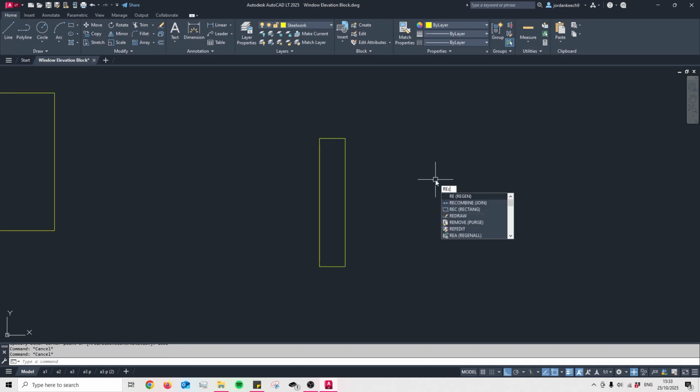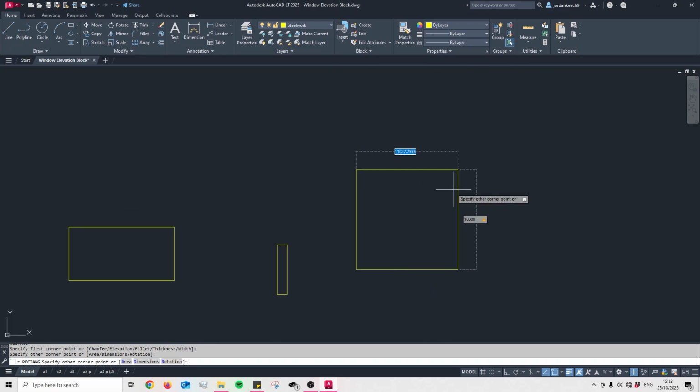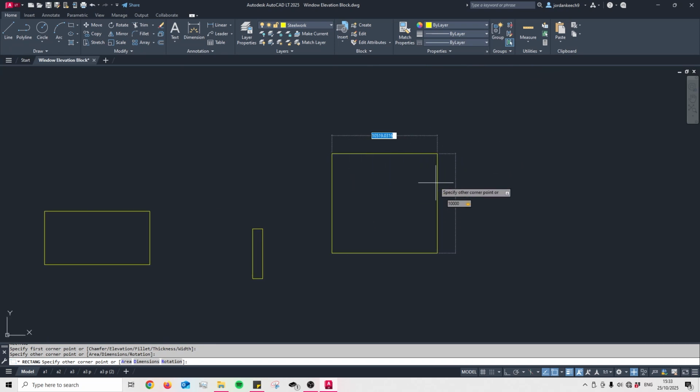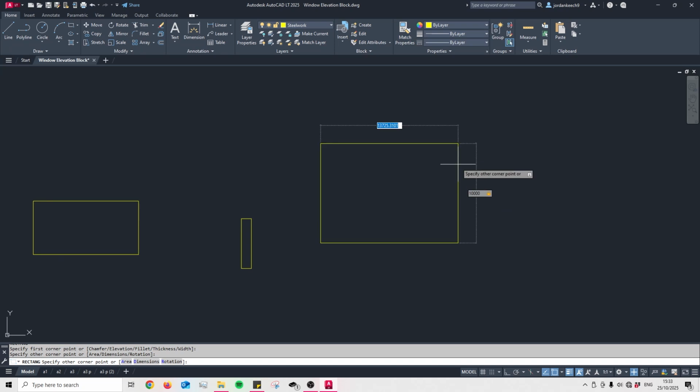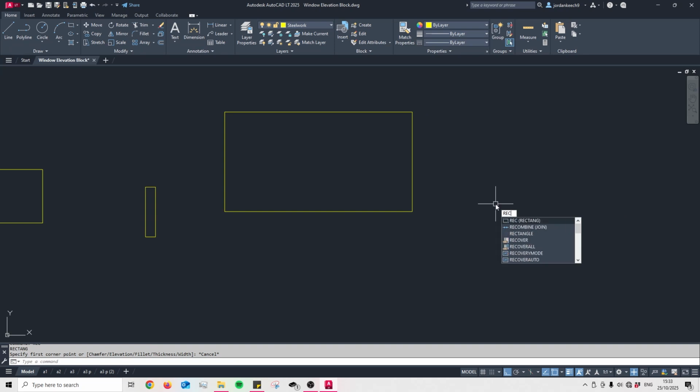Something to note is if you just input one of the lengths on a portion of the rectangle, one side will be locked after pressing tab, and then you can move the cursor around and only the other input will change. Here you can click again or type in your other value. So that covers how to place a rectangle, but when the rectangle tool is open, you'll notice that at the bottom of the screen there is a number of options that appear in the command line.